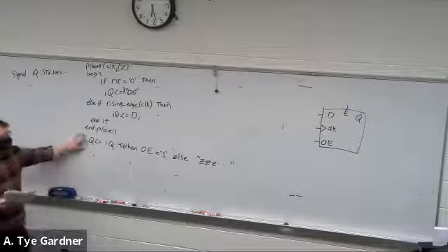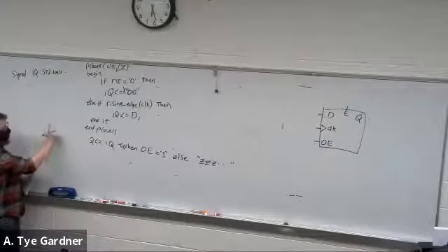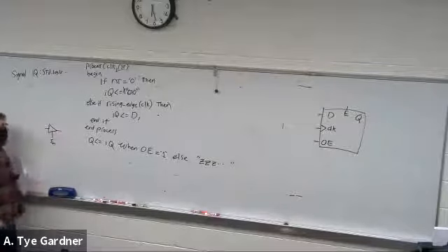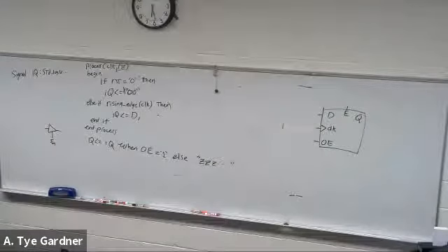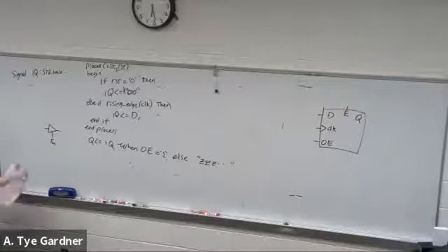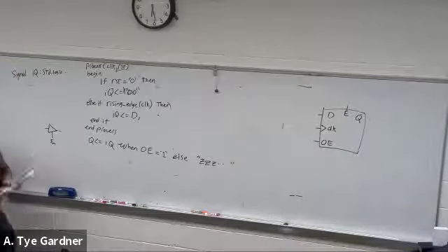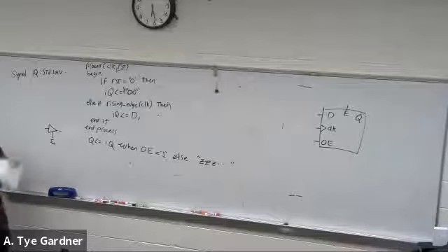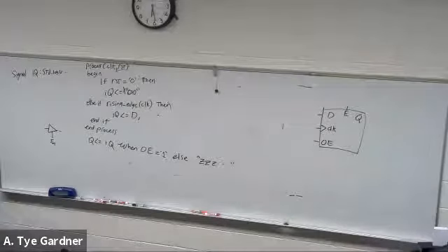What this is doing is creating that buffer that is just saying, if I'm not enabled, we're just going to disconnect there and break it, and it can do whatever it wants. We're not going to drive our value onto it. So that's how we make an output enable.